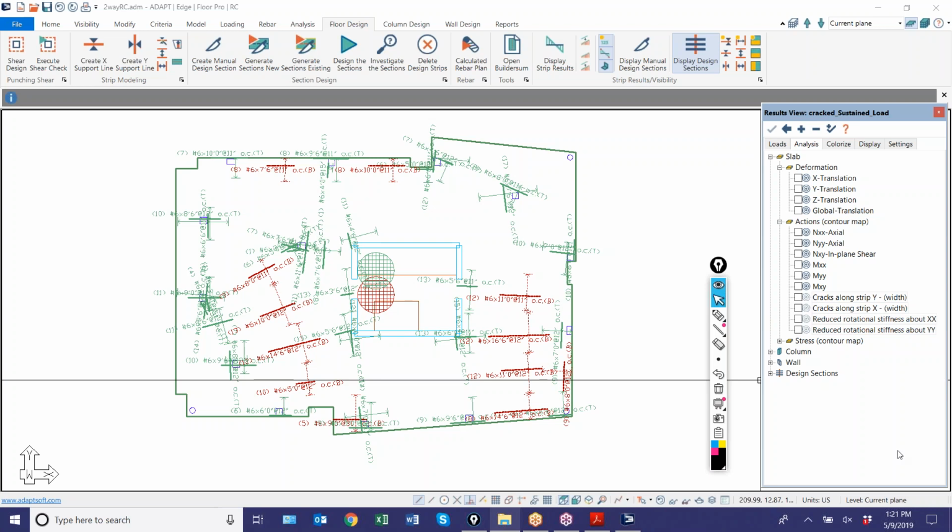The question was, for crack deflection, does the program include the reinforcement contributions? It includes it, I would say, indirectly, because we use the bilinear relationship between Ig and I effective, which is dependent on the cracked moment of inertia, which considers the presence of the rebar. But